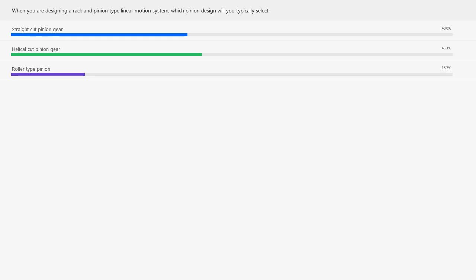As Roberto mentioned during the event, using a helical cut pinion and rack system not only induces separation forces that the reducer will see as a moment load, but because of the helical structure, you will also see an axial push or pull in and out of the reducer. So having sufficient bearing capacity not only to contend with separation, radial, or moment, we also have to think about the axial load in its consideration as well.